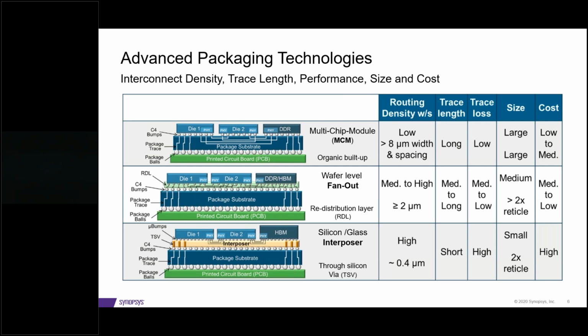These are not your traditional semiconductor level RDLs that are done as a fab process when the silicon is done. Yes, it's a polymer, and it's post-fab. So your silicon manufacturing, your CMOS device SoCs, is already done, and then you put this layer down on top of it.